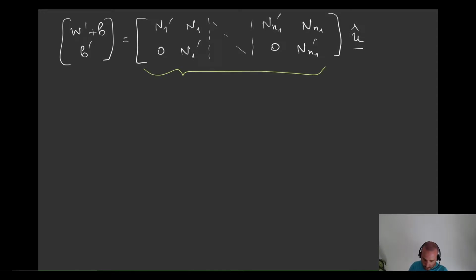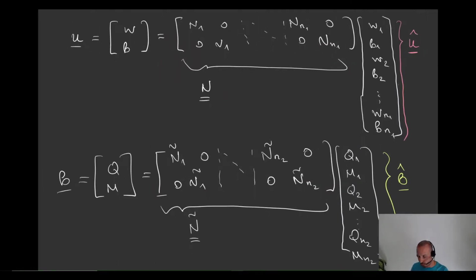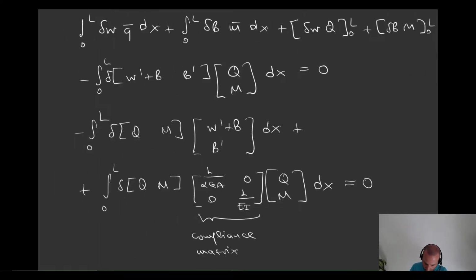the B operator matrix, when we discretize, if you recall, the strains for the Timoshenko beam and the Reissner plate later. Okay, now since we have these three matrices, which are all the matrices we need, we don't need more than this, we can go ahead in the second equation that we laid out before, that one here. And please let me give also a name to this compliance matrix. I'm going to call this one S with double underline because that's a matrix.